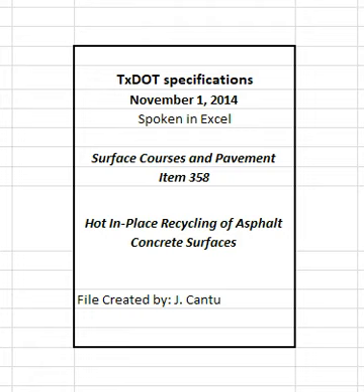3.1.5 Paving Unit. Furnish a paver or paver screed meeting the requirements of Section 320.2.3.1, Asphalt paver. 3.2 Rollers. Provide rollers meeting the requirements of Article 210.2, Equipment. 3.3 Broom. Furnish rotary self-propelled power brooms. The broom should have positive control on the downward pressure applied to the surface.